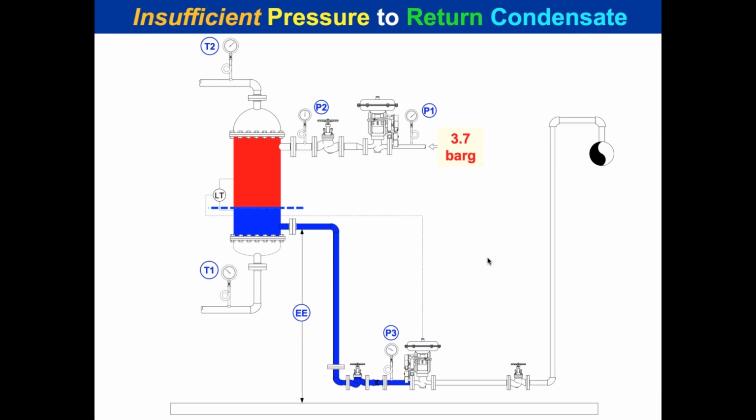Here's this thermosiphon reboiler that this engineer had, 3.7 bar steam coming into the reboiler. The reboiler was designed and built like 10 years before, and it was way over-surfaced. So what happens is they had way more surface area than they needed. The condensate level was really low. Your back pressure over here to the right is 1.8 bar.